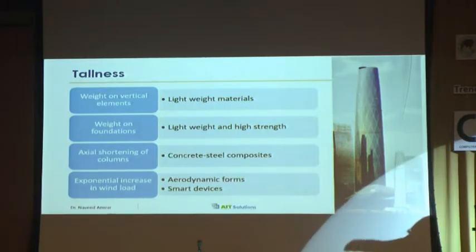If you just take steel and hang it from the top, there will be a length of the steel that no matter what you do, it will just break by its own weight, because its cross-section area, its strength, and its density are all related. So there is a theoretical limit on how long a bar or wire you can hang from some point. The same is the case in compression. There is a limit on how tall a column can be just to support its own weight. After that, it will crush under its own weight. You can easily calculate that based on f'c or whatever you want to use. But there is a limit.